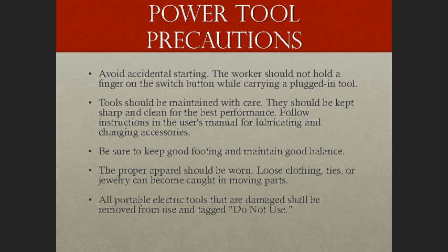Avoid accidental starting. The worker should not hold a finger on the switch button while carrying a plugged-in tool. Tools should be maintained with care according to the manufacturer's written recommendations and should be kept sharp and clean for the best performance. Follow all the instructions in the user's manual for lubricating and changing accessories.